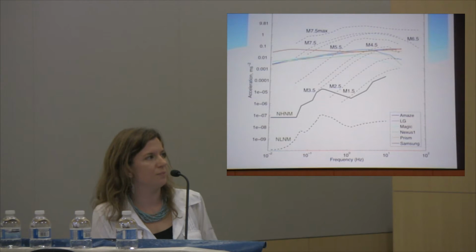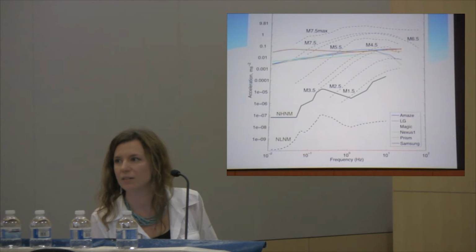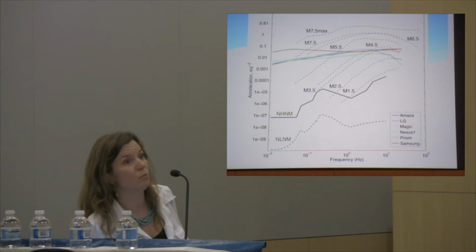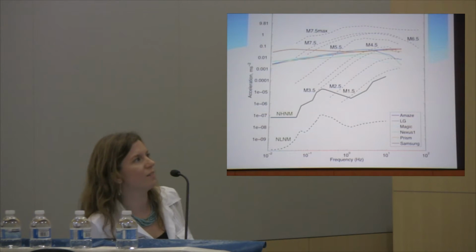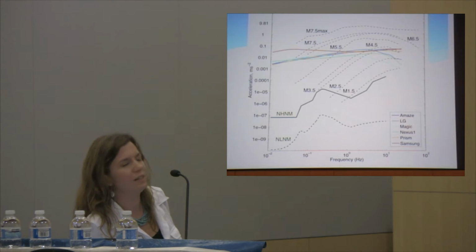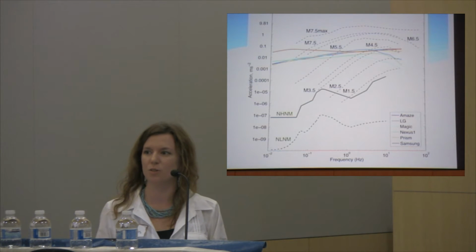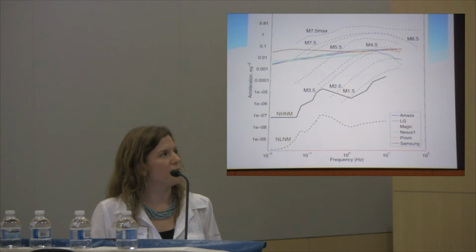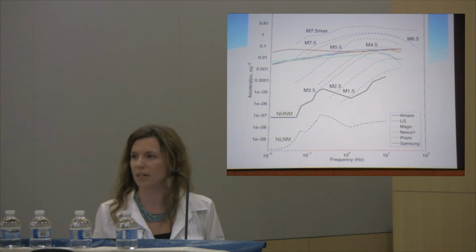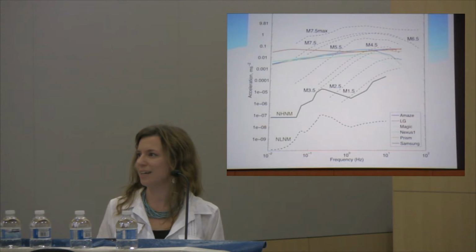So we took about 6 different brands of cell phone and did some noise floor tests on them. And so this is what we came up with. This is about as good as you can get, perfect, ideal world. This is your noise floor of your accelerometer in your cell phone. And so at first you say, well, that's actually pretty high, Jen. Like, what is that getting me?